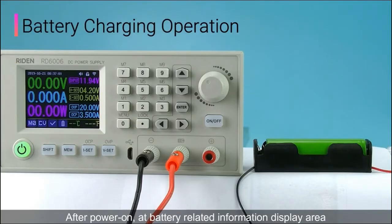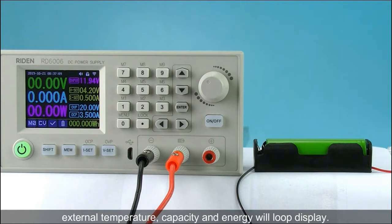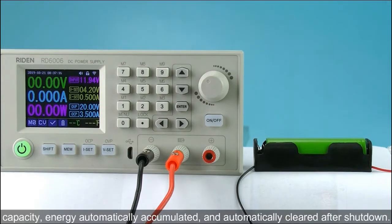After power on, at the battery-related information display area, external temperature, capacity, and energy will loop display. When there is output current, capacity and energy are automatically accumulated and automatically cleared after shutdown.